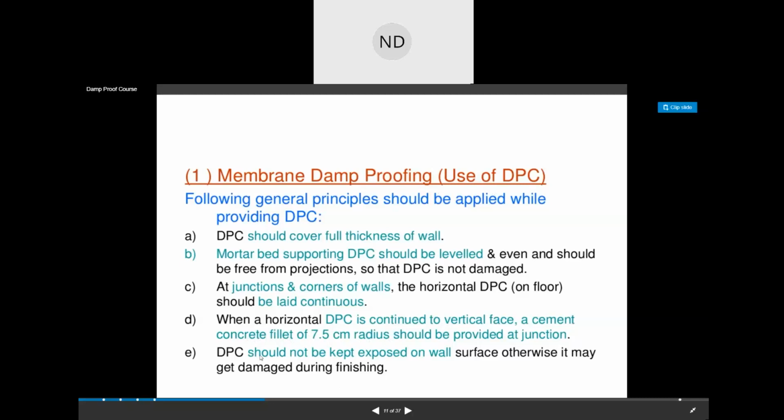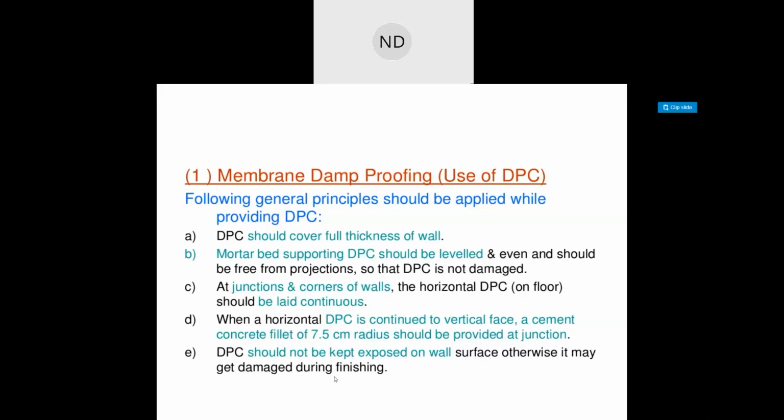The next point you have to apply is that DPC should be kept exposed on the wall surface, otherwise it may get damaged during finishing. It should be exposed on the wall surface.